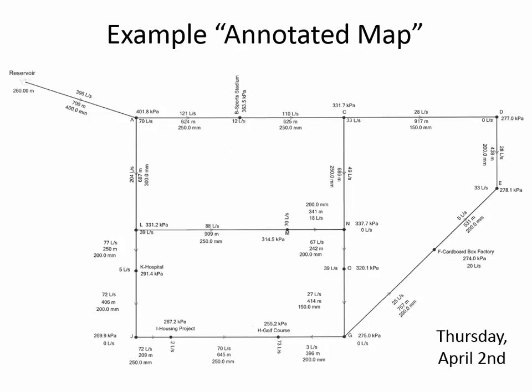Static, right. So the static map is when there's no flow through the system, and so that's when you're going to see high pressures in the network. And so if you're doing your analysis where all of the demands are set to 0, that's what you have to do to analyze it at static conditions, and you're seeing like 900 kPa, that means don't change the pipe sizes. If you see any places over 850, that means you have to bring the reservoir lower down on the hill.